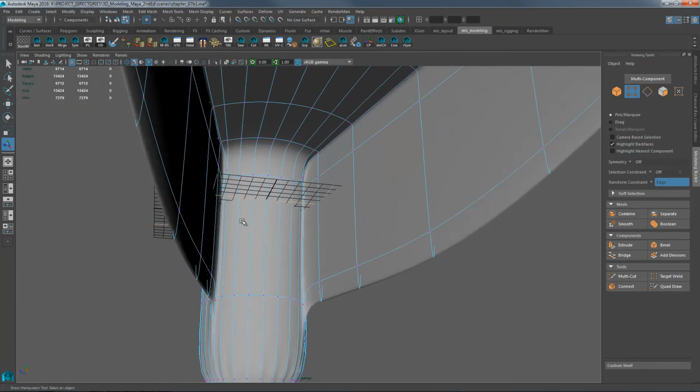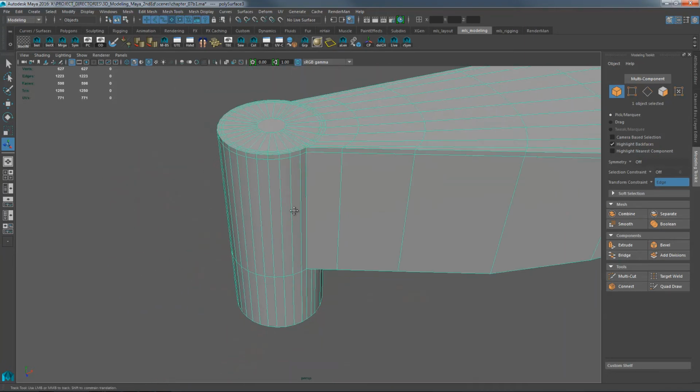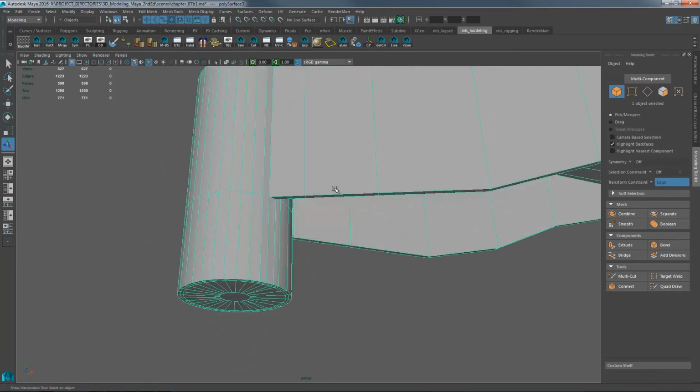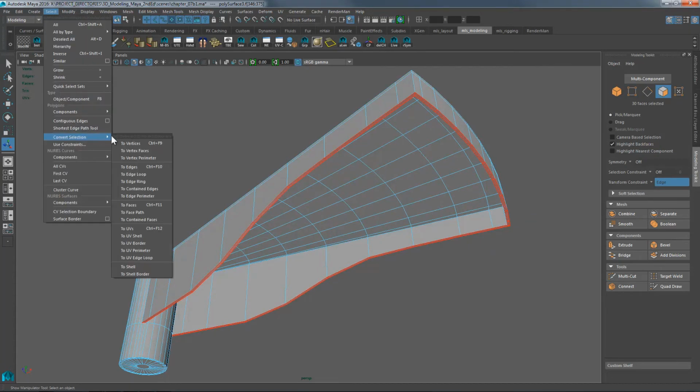supporting edge loops. Okay, here I have done two extrusions, 0.25 extrusion, 0.25 extrusion, then a third extrusion towards center, arbitrary distance on offset, and I'm going to leave the n-gon there. Then I'm going to add a supporting edge along the bottom. For the bottom, I'm going to select all the polygon strip on the bottom and then convert that selection to edges. Convert to edges or Control F10.